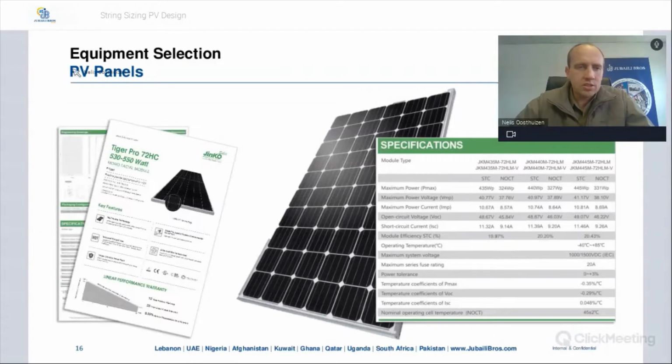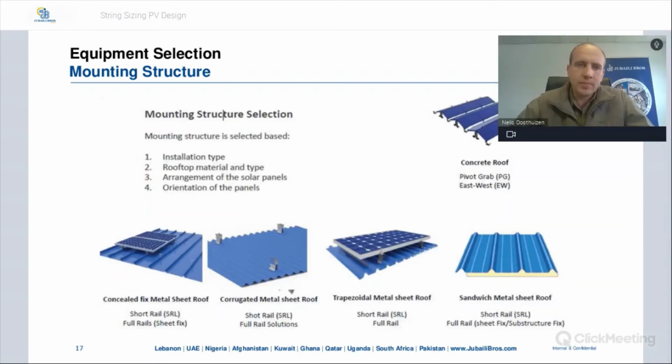Again, this is just continuing on PV panels. You've got STC as well as NOCT ratings. STC ratings are almost lab conditions, at standard temperature, but NOCT ratings are your normal operating temperature ratings. Normally for design, you use STC ratings, although NOCT ratings are closer to reality or what's going to be in practice. Mounting structure, that's your third equipment selection.